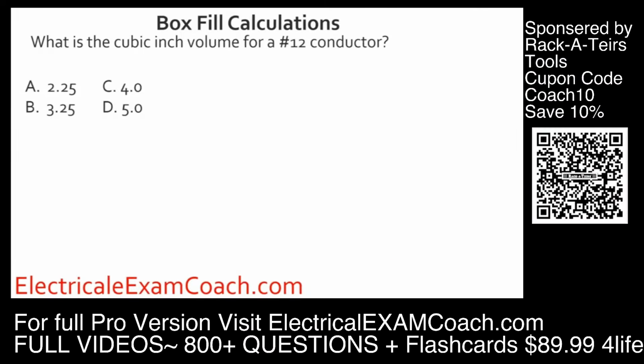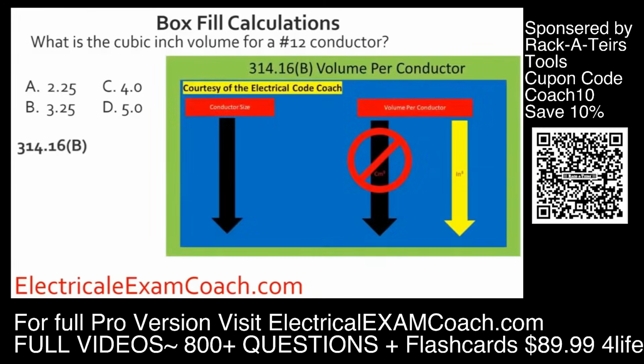What is the cubic inch volume for a number 12 conductor? Head back to 314.16(B), start on the left-hand side and find our size conductor, then cross over to the cubic inch volume, and it's stating that every number 12 in that box, according to the count, which we're getting ready to learn, takes up 2.25 cubic inches of that box.